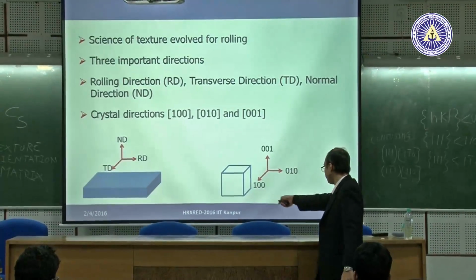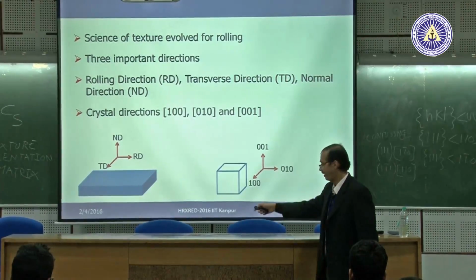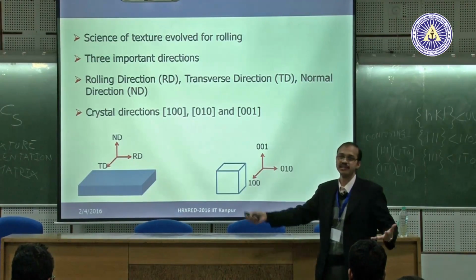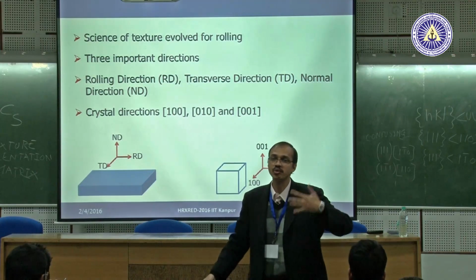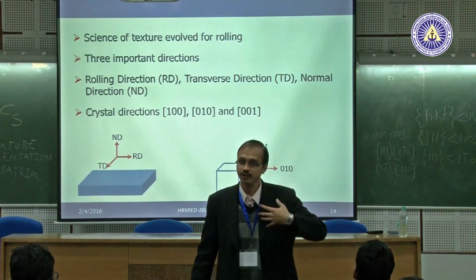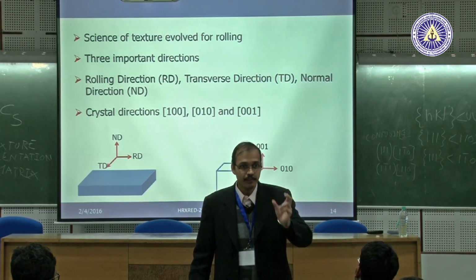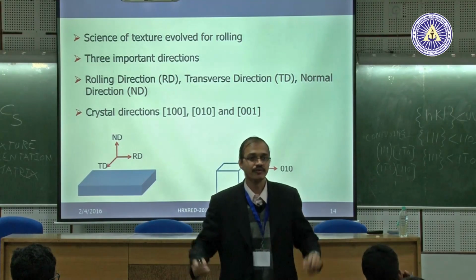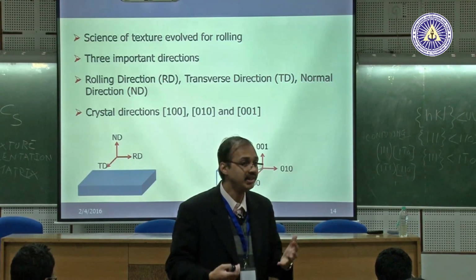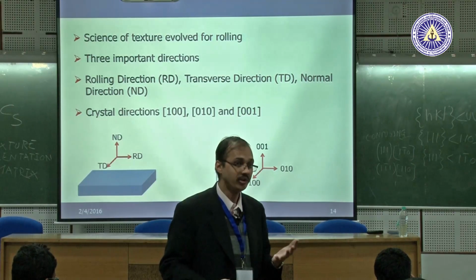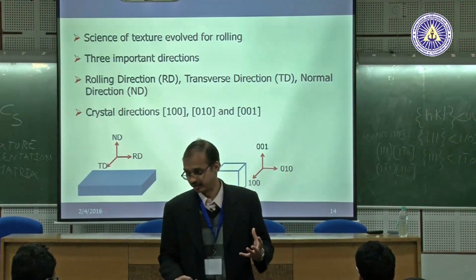Remember, this is in angstrom, this is in meters. And in between there you have grain size and so on and so forth. So as your grain changes, this HKL UVW is going to change. Why we use X-ray, I showed you those colorful images. But those are very small. You have millions of grains. So if not millions, you want to scan or interrogate at least a few thousand grains. And that you can do only using X-ray diffraction.